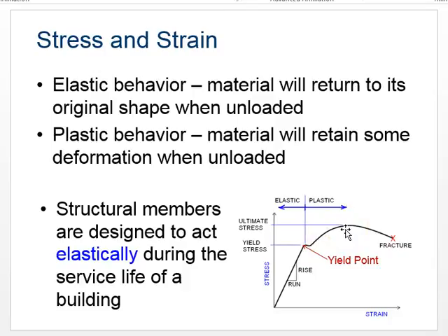This is a plastic region, think of a plastic water bottle. Once you've bent it, it's never going to go back to its original shape. What happens is we hit the maximum yield here, and then you can keep adding more strain to it and pulling on it, and eventually it fractures. Add this point to your graph.